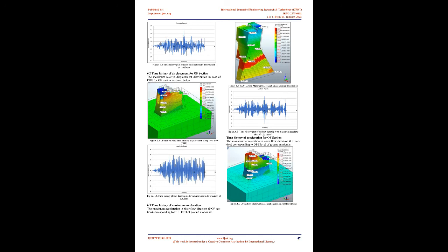7. In case results of linear elastic analysis indicate significant damage to the structure, stresses significantly exceeding the permissible limits or exceeding in large regions, decision based upon rational engineering judgment will be taken to provide a reasonable estimate of the expected inelastic behavior or damage.